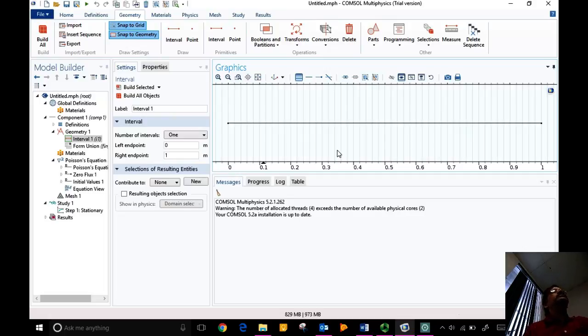What was the difference from the previous equations where we used zero dimension, but here we're using one dimension? When you have zero dimension, it says that there is no variation in any spatial dimension. This is what we call the lumped model. So things can be either constant, homogeneous everywhere, or varying with time. Like in the CSTR problem, even though you have a reactor, the assumption is every place inside the reactor has the same composition and same temperature. It's not true, but it's an assumption.